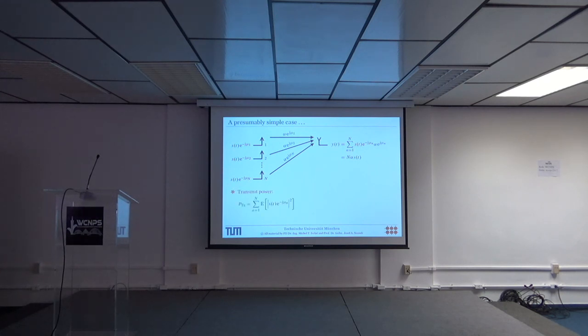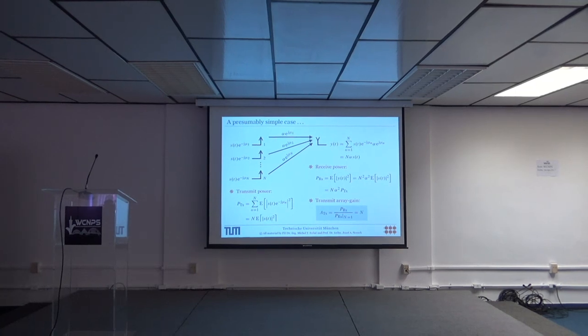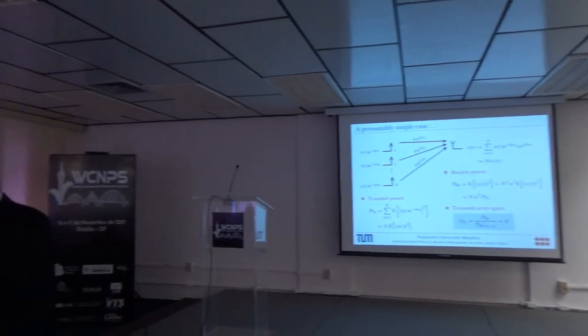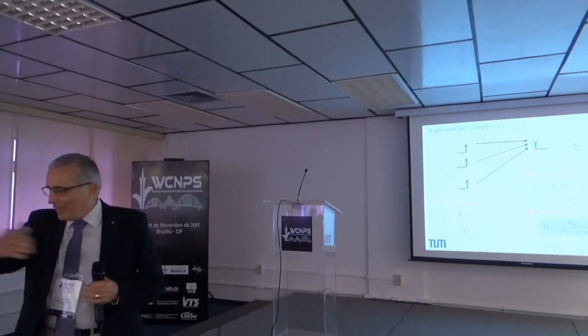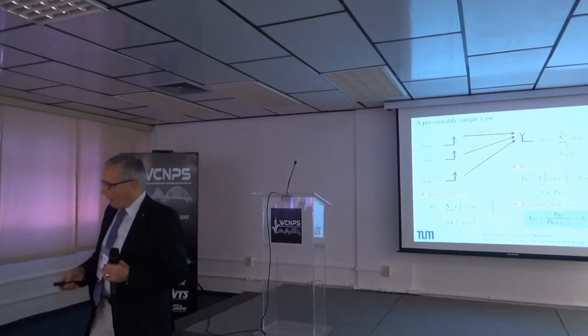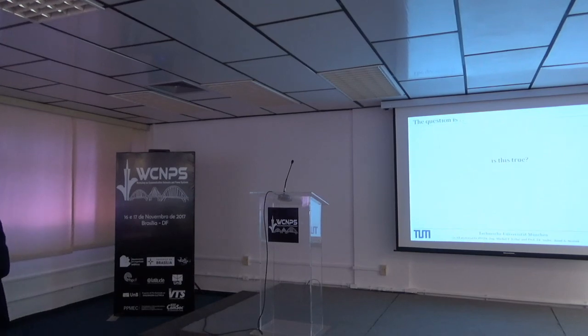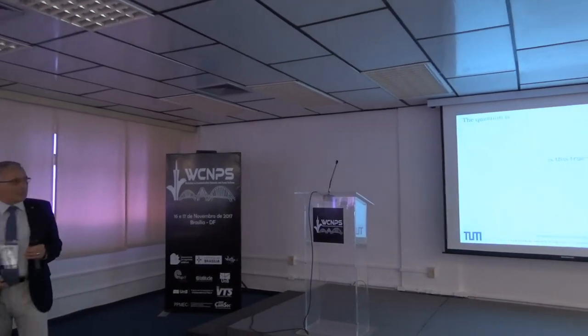I can go quickly through that calculation and come up with the fact that the transmit array gain will be equal to the number of antennas. That is, again, a standard thing everybody knows in signal processing. And it doesn't depend on the direction in which I would produce that gain. If the array is a uniform linear array, for any direction, front fire, end fire, it will always be the same antenna gain. Question, is that true? No, it's not true. It's only true in very special cases.